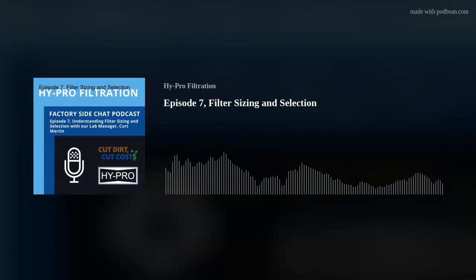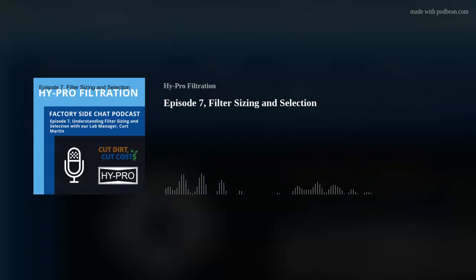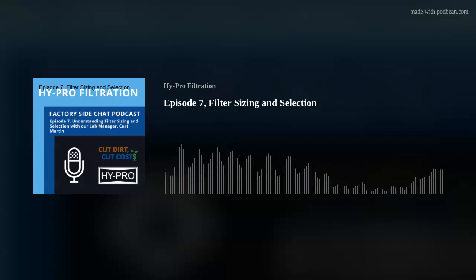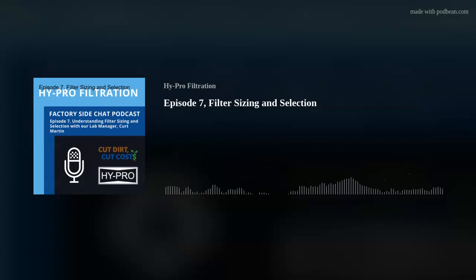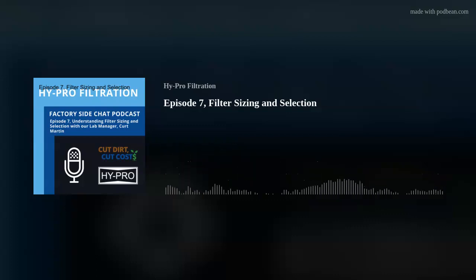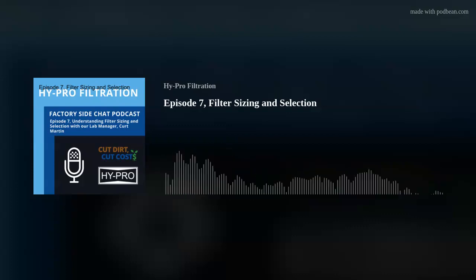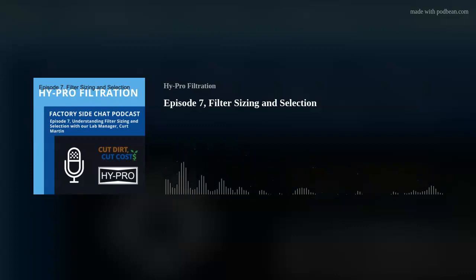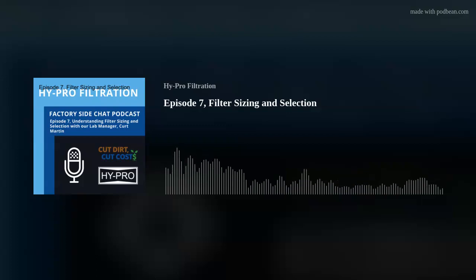Yeah, the bypass valve. That's there as a safety feature. Once the element reaches the bypass valve setting, the bypass valve will open and relieve the pressure. It will help reduce the risk of the elements collapsing. It doesn't always prevent it depending on the scenario, but it greatly reduces the risk.